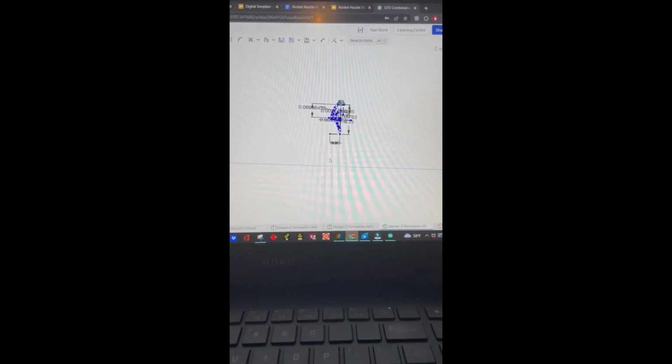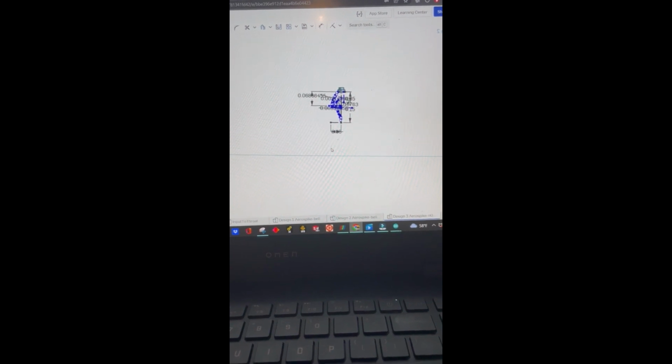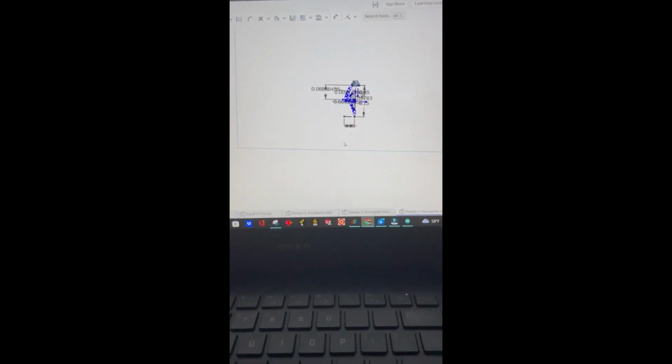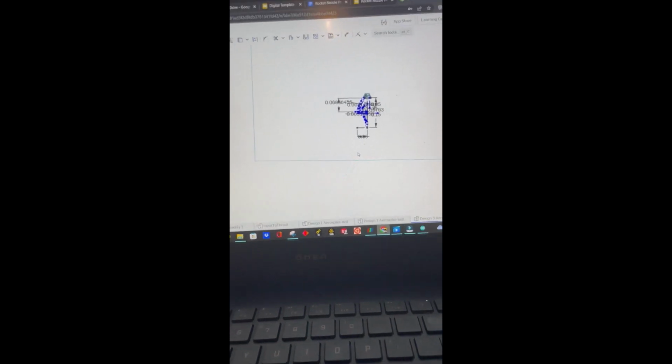In order to test if my theory of cosine loss cancellation will work, we can first start by benchmarking some of the more common geometries like the aerospike and bell nozzle that was mentioned before by using something called CFD, or computational fluid dynamics. Essentially, we'll be applying some partial differential equations such as Navier-Stokes, and we'll be using something called the k-epsilon turbulence model in order to simulate the flow around our nozzles. For this, we will be using the OpenFOAM solver.